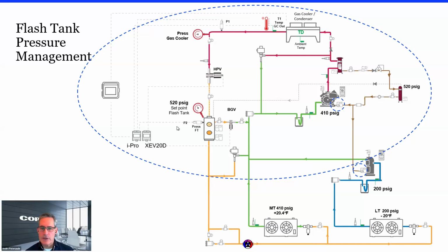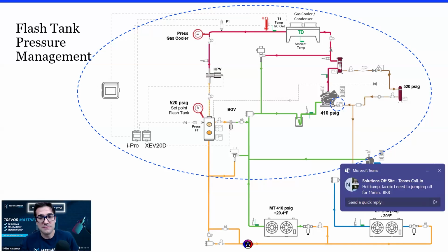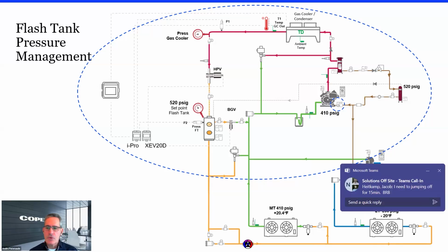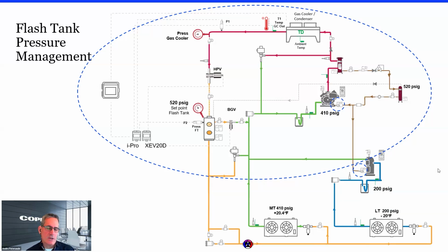Yeah, no, absolutely. And flash tank pressure, of course, is just like a receiver pressure in an HFC system because it is a receiver. So if its pressure is really, really low, then of course the pressure drop across all the expansion valves on your system is very, very low. Yep. That means its flow rate is lower and the superheat is higher. So things are interrelated. On an HFC or a CO2 system, you've got to think about that inlet pressure, liquid quality, and the impact it has on other parts of the system.